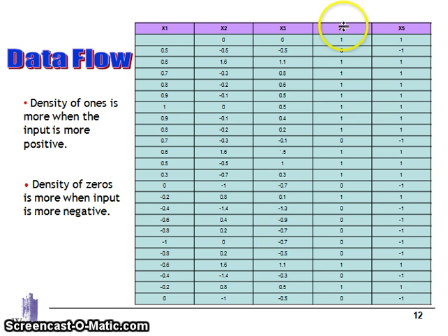And x4 is either 1 or 0 based on whether x3 is positive or negative. Here it is negative, so the output is 0. If it is 0, then the output of D2A will be minus 1. Right? Now this process continues like this till we get a final solution.